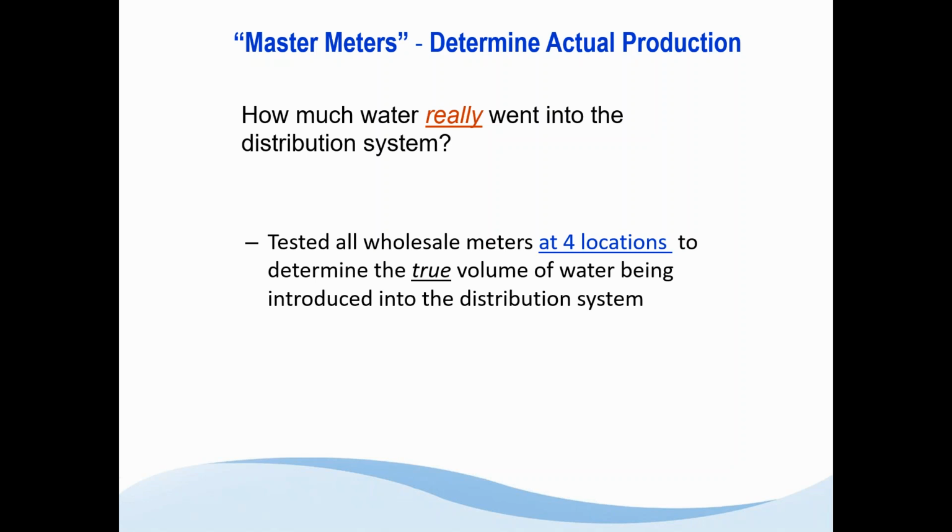This was critical, testing those meters, and let me advise everyone that in the case of production or master meters at your facilities, testing the 4 to 20 milliamp signal between the head of the meter and your SCADA board or your computer is not a meter test. It's certainly an important test of the signal between those 2 items and that it's transferring correctly, but it had nothing to do with the water meter and its accuracy.